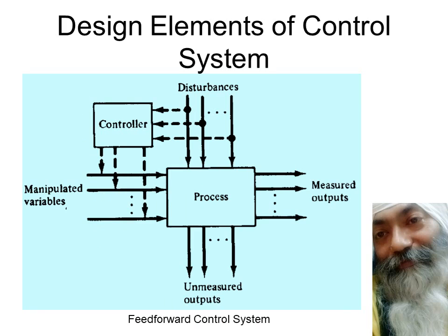And this is the third configuration and perhaps the last one as you're going to discuss in answer to this question, that this is the feed forward control system. What we do in a feed forward control system, again you have a process and you have some disturbances taking place, but feed forward control is possible only where the disturbances are measurable. You are able to measure the disturbances.